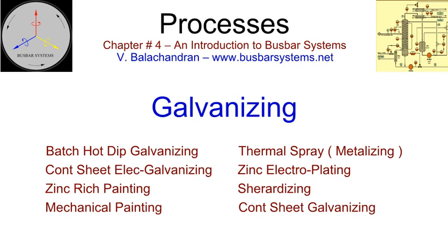Steel reacts with oxygen in the atmosphere to form iron oxide, rust, which is a stable compound. Steel will also corrode through galvanic cell formation, in the presence of moisture, due to non-uniformity in the surface composition. This process of corrosion continues until the entire steel is consumed. Steel is protected by the galvanizing process in many ways. It forms a protective skin around steel and prevents interaction with the atmosphere.